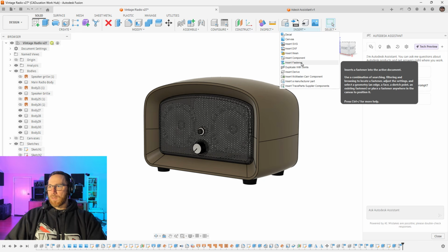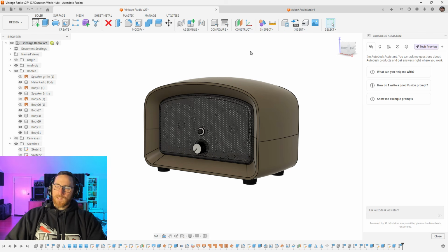And so if you're using things like Insert Fastener, which is a dedicated tool inside of Fusion, theoretically, it could have the ability to replace all the fasteners in a design with the same head style, same length, same thread pitch, but switch materials. That could be something that, if it works, could save a lot of time.